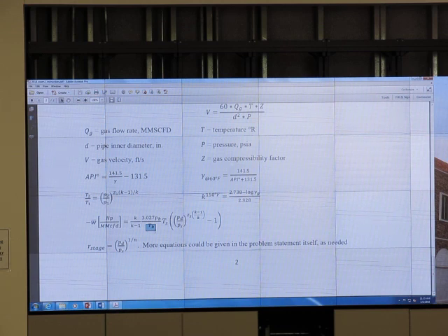What is the unit? Rankine, correct. TS, suction temperature. Rankine. PD, discharge pressure, and suction pressure, PSIA. Okay. The compressibility factor is not much, it's just this, right? Put everything in and get horsepower per MMSCFD. Very easy. And what about this? PSIA. Put it in if you know the compression ratio. This is compression ratio, right? And then you can get discharge temperature.